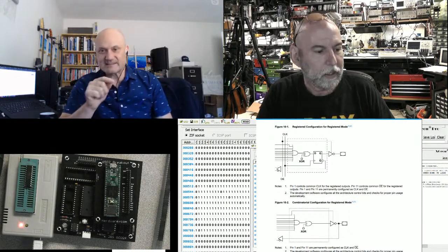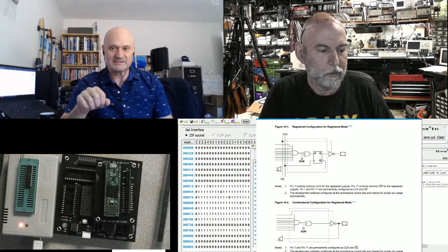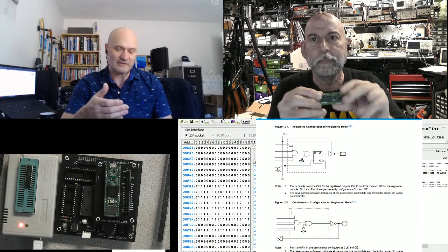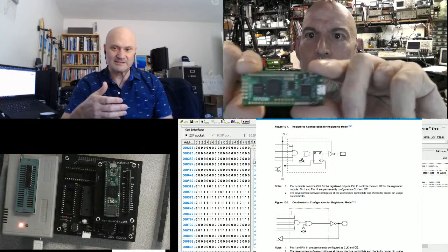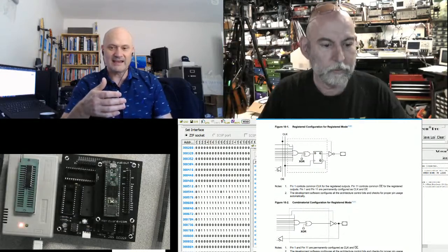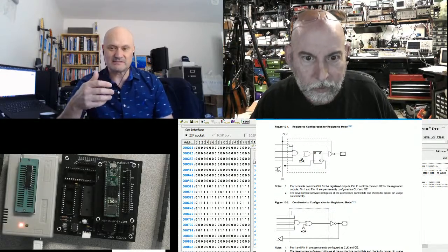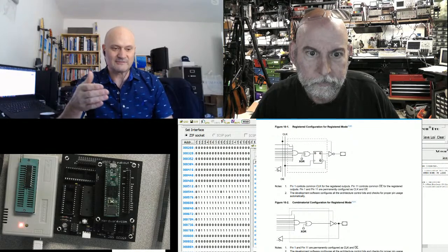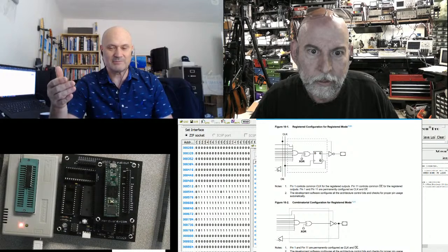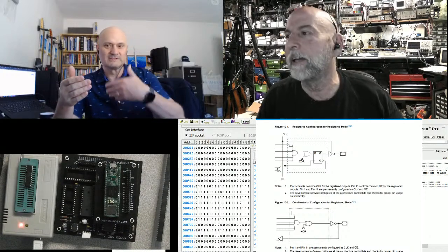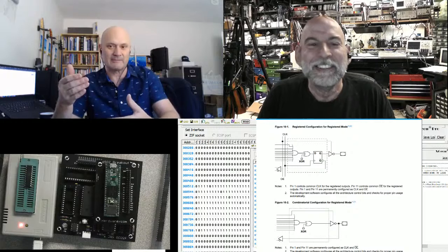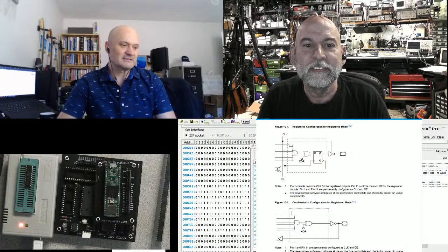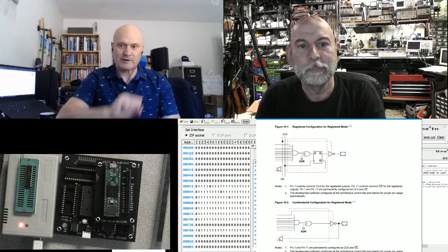So that's how it was. They were PLDs that used product terms and electrically erasable or flash-based, floating gate technology. And I think they've gotten so dense that some of those devices have switched to RAM-based FPGA under the hood with a built-in flash for programming them on power up. And they just call it instant on, even though it isn't really. It still takes a millisecond or so to program the whole thing.